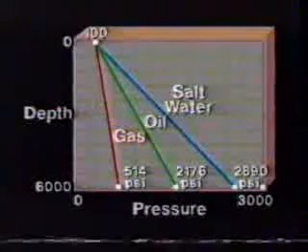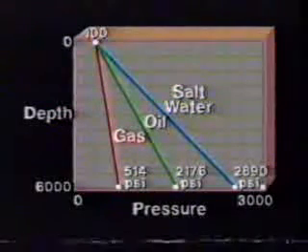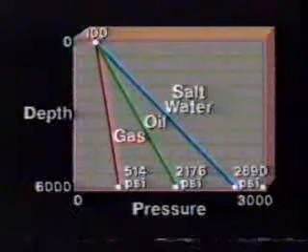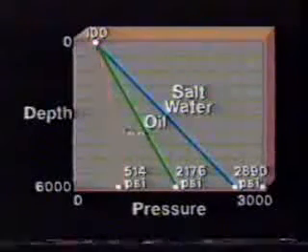The pressure profiles for the conditions obtained in each well are shown graphically here. We see the very low bottom hole pressure that exists when a well is filled with gas. We conclude from this that if we have a well filled with oil or water and can saturate all or a portion of the liquid column with gas, the bottom hole pressure will be reduced significantly. With a reduced bottom hole pressure, fluid inflow from the formation will be increased and perhaps become continuous.